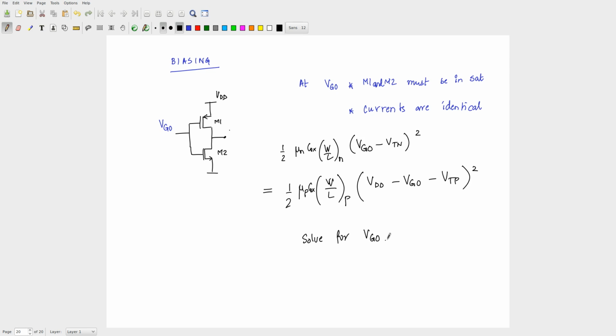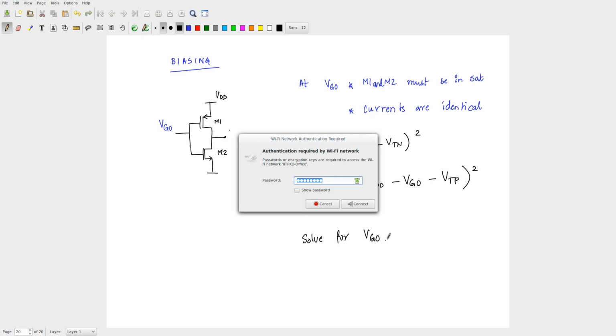The next point we said was that you can in fact get infinite gain if both the NMOS and the PMOS transistor had absolutely flat characteristics in their saturation. And finally, we said that you can get a very simple looking circuit, which is the CMOS circuit, which just has one NMOS and one PMOS transistor, and that is your common digital inverter. It is difficult to operate that as an amplifier because you have to bias it exactly at the transition point, and we will see how to do that in a subsequent course. But I guess this gives you a flavor of what you can do if you have both the NMOS and the PMOS transistors in your circuit. All right. Okay. With that, we will close for today. Thank you.